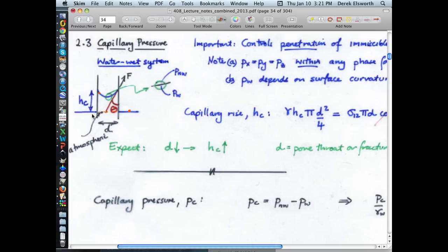If you know that, then you could actually cut off the bottom of this tube, and you could make a tube that looked like a free body, which is this, where this is the height of the tube, this is its diameter. You have to apply some kind of force here to be able to lift it up, and you can resolve the forces on this. And so what we're doing is you're just cutting off the bottom of the tube, picking it up, and seeing if we can balance the amount of force that we have to apply here in the vertical direction versus the weight of the fluid which is coming down here. So that's all we need to do.